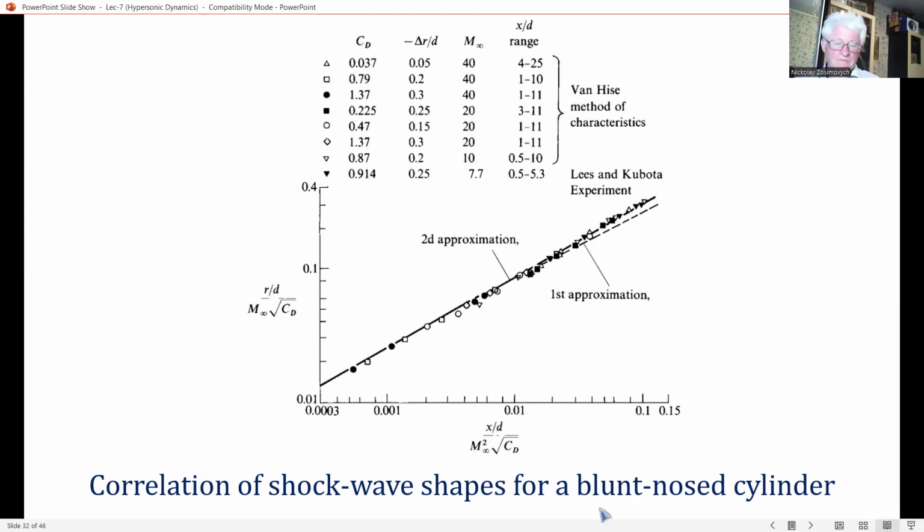So, a comment is in order now. The analogy between unsteady blast wave flow field and the steady hypersonic flow field over slender, blunt nose bodies is somewhat tenuous on physical grounds, mainly because of the assumption in the classical blast wave solution of instantaneous energy release at a point or line in space.